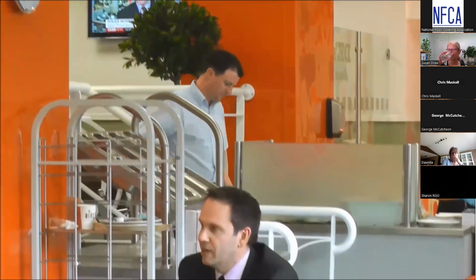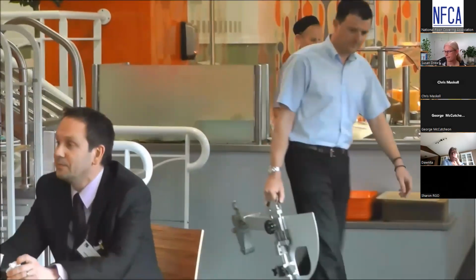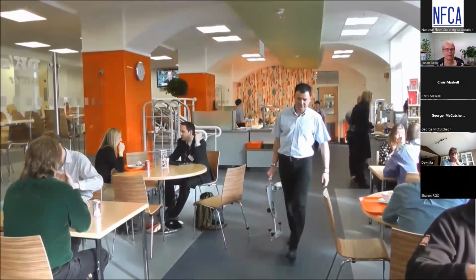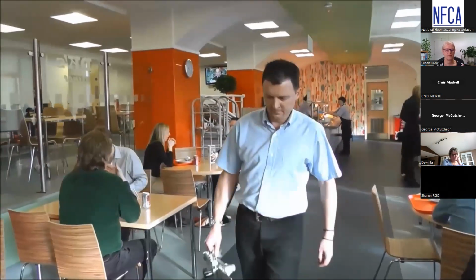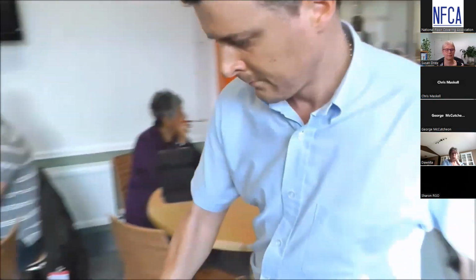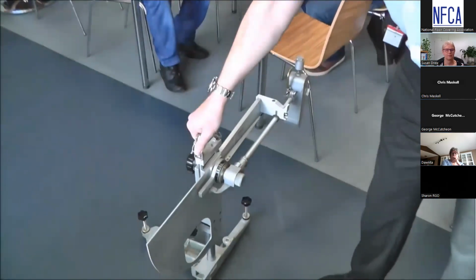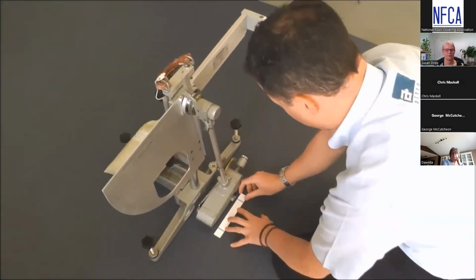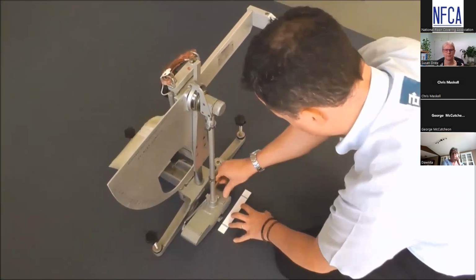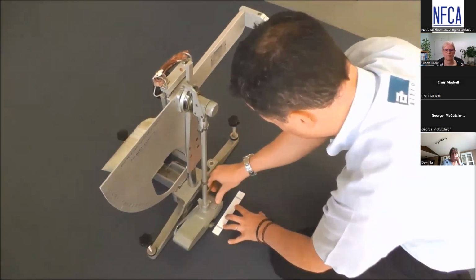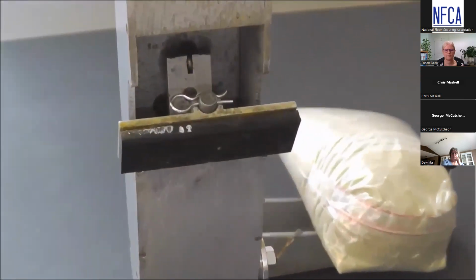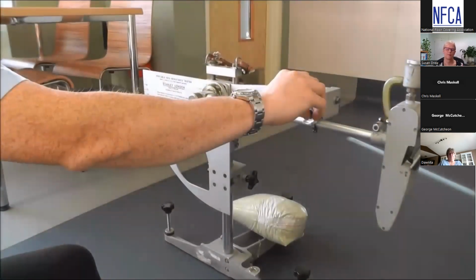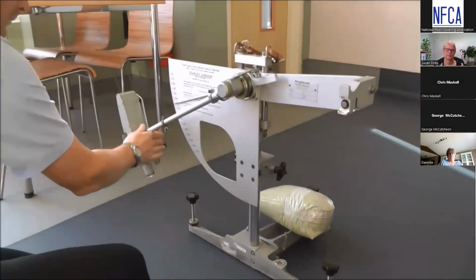The pendulum coefficient of friction machine is portable and can test the product at any time in situ. Although the test is used globally, it is especially popular in the UK as it is endorsed by the Health and Safety Executive and the United Kingdom Slip Resistance Group. The pendulum mimics the act of the heel striking the ground during walking. A specially formulated rubber slider on the bottom of the swinging pendulum arm sweeps across the floor surface and records the drag.